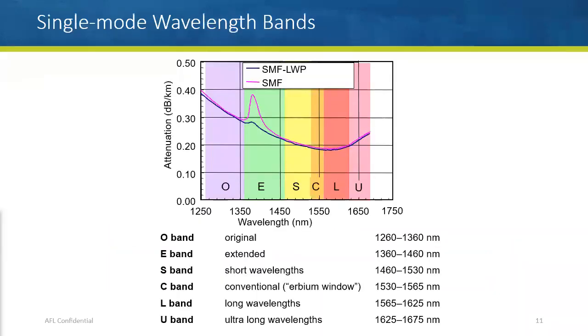But on this slide, you can see that there's actually multiple different wavelengths that are available in different bands. And the attenuation is basically how far down, how long you can go before you end up with issues. So how much loss is there in the signal strength, or the strength of the light as it's running down the fiber. And this is actually a really good graphic to talk about some of the other applications for single mode fiber. And that is typically on the telecom side.